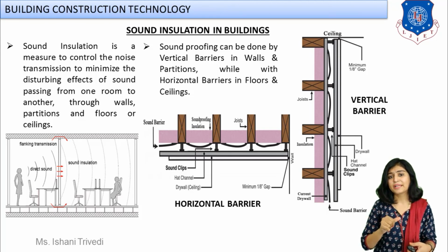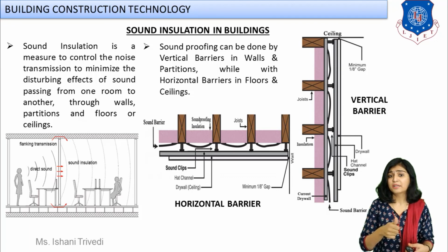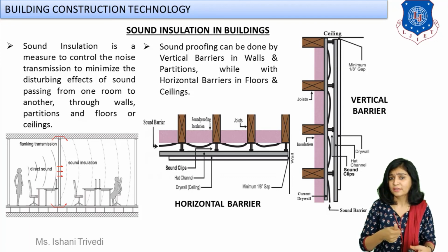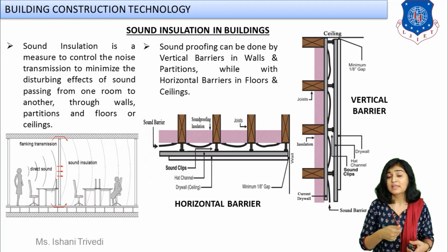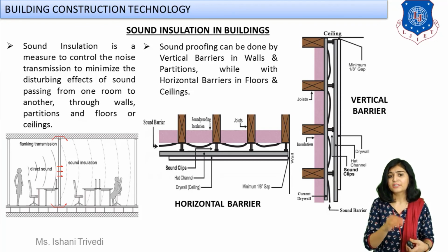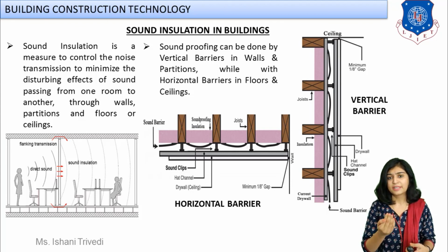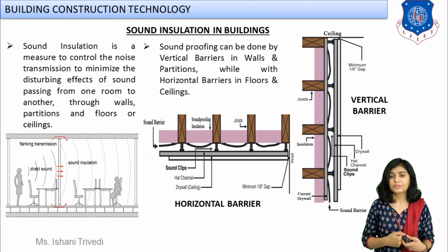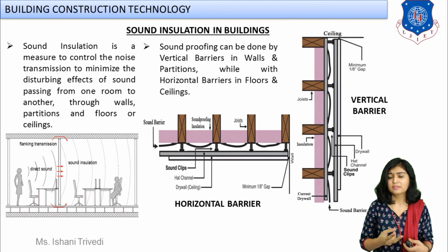Now see students, if I give you example of a floating timber floor. I told you that floating timber floor is generally common these days. Also one point, that timber flooring always creates noise. If you step on it, then it is going to create a noise. So for that, in between you can provide a barrier itself, a structural member itself. So it is going to absorb the sound, and hence it will make your structure sound insulation. Okay students, so this covers your special treatments regarding the thermal insulation, the sound insulation and fire resistance.